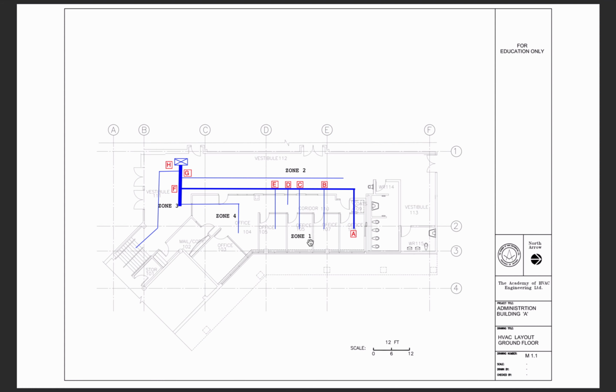There is a critical path that is usually used to size the ductwork. It's the longest path. Let's split it into sections. So A to B is one section, from B to C is the next section, the next section C, D, D, E, E, F, F, G, G, H, and from H to the air handling unit itself. Now let's go back to the tab ducts.